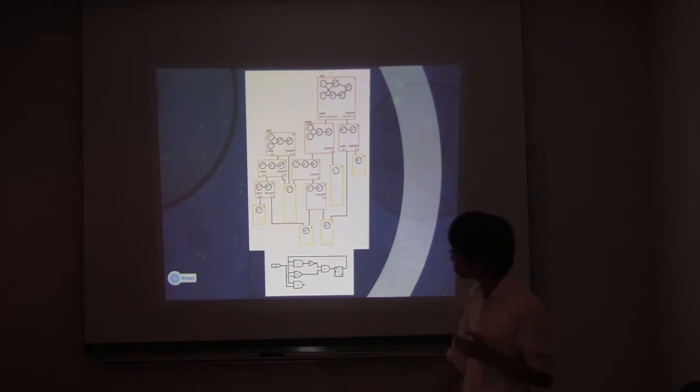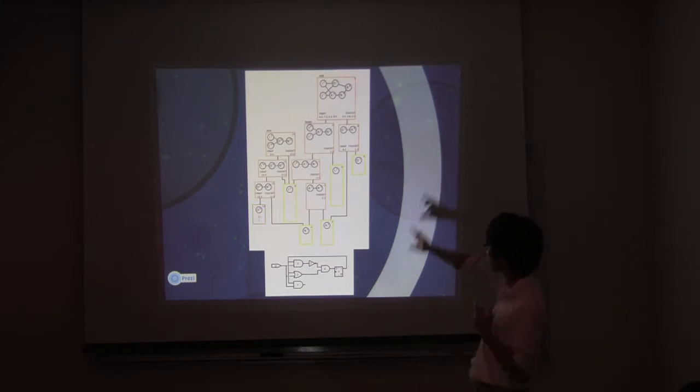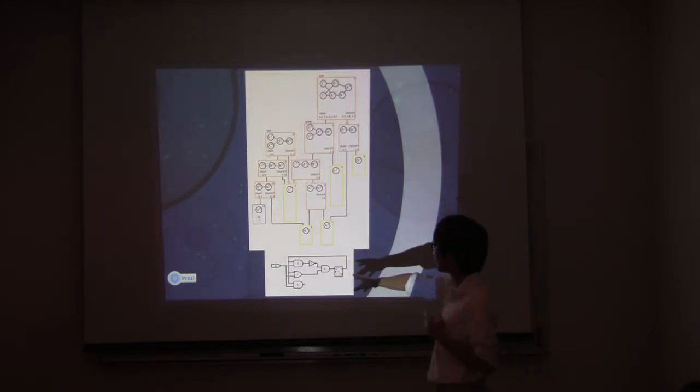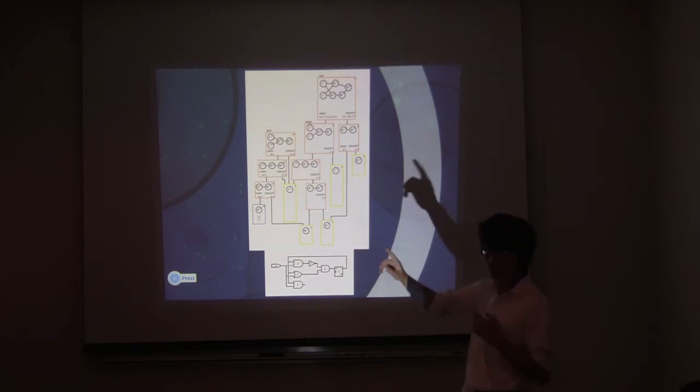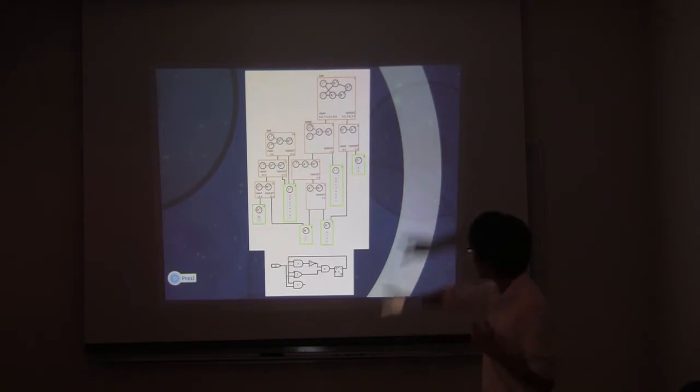So initially, we look at the vertices, the nodes that contain a single vertex. We then try to find a mapping between that single vertex and the components in the circuit. So in this case, there's one OR gate in the circuit, so we map that OR gate as a possible match with that one component. We go through each of the single vertices, and we find a one-on-one mapping on the circuit.